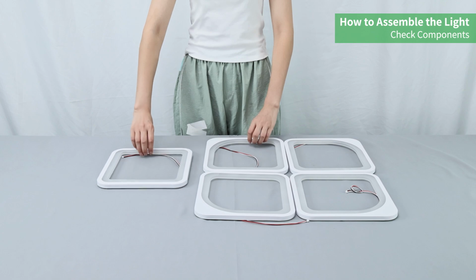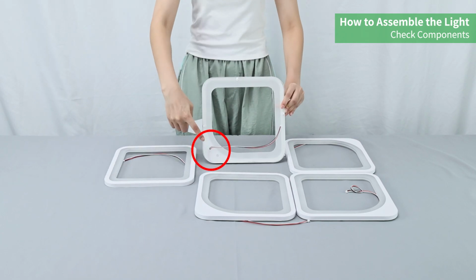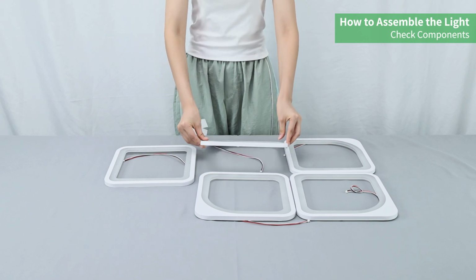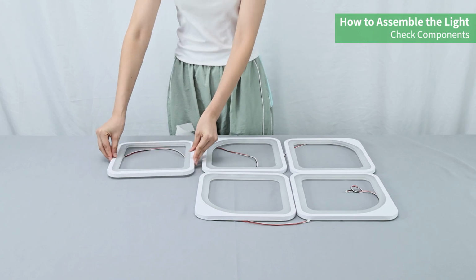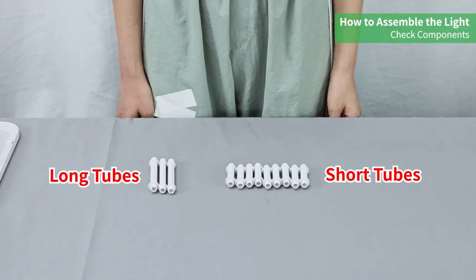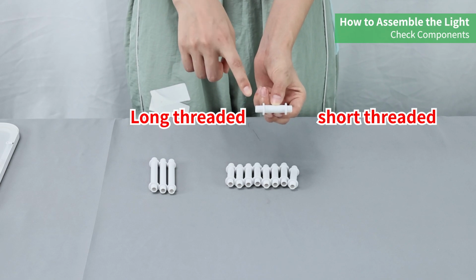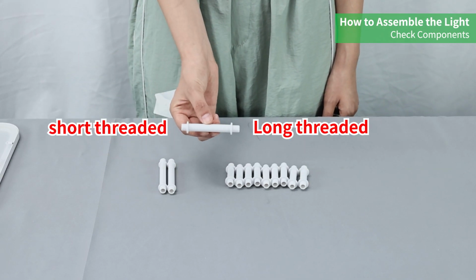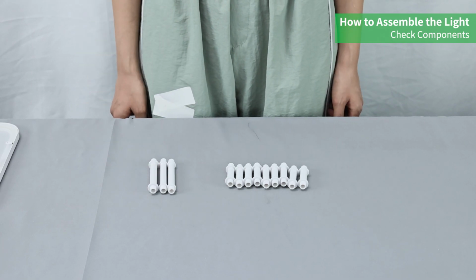This shows the difference between the two types of components from the front. On the back, the light hole positions of the perimeter square components and the center component are different, so please distinguish between the two components. The fixing tubes installed on the square components come in two specifications: long tubes and short tubes. This is the short tube, which has a short threaded end and a long threaded end. The long tube also has a long threaded end and a short threaded end. Please note the difference between the long and short ends of the fixing tube.